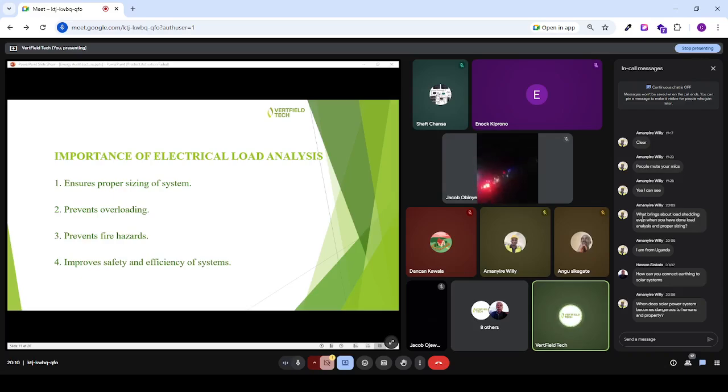I don't really get that clearly, but for you to size the inverter system that will be able to carry your facility, when you talk about your kVA, it is from this load analysis, it is from this energy need of the facility. So when we size the energy need of a facility, you will get to see how to size the inverter system.